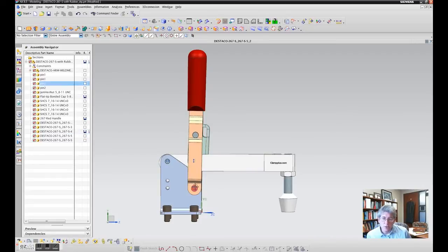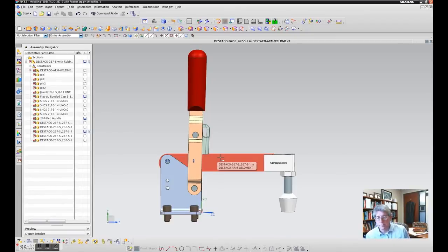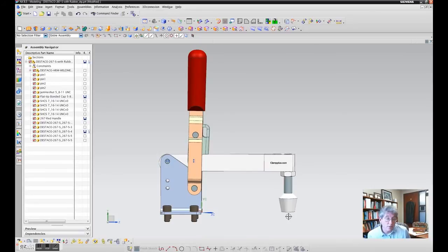Once the clamp is over center, actually if you look really closely, the way this works is you can see these two holes don't quite go vertically. This link just swings a little bit over center, which locks the clamp down. So kinematically, it's such that you can't unlock the clamp by putting force up here. Theoretically, it should take infinite force to disengage it, but obviously you have structural failures that limit that clamping force. But another situation would be somebody exerting a significant amount of force on this handle, okay?